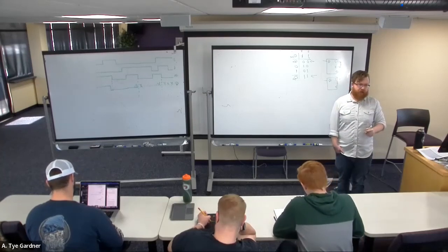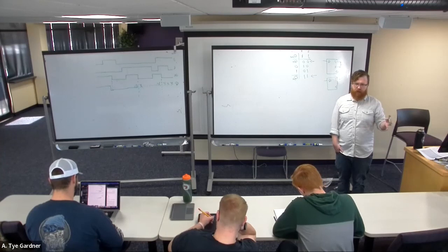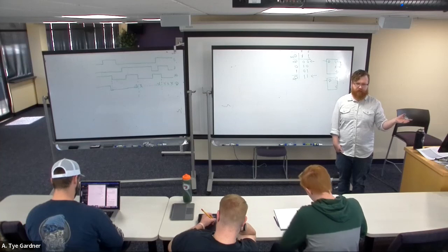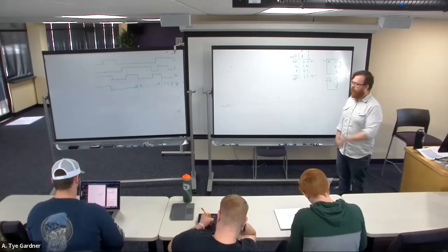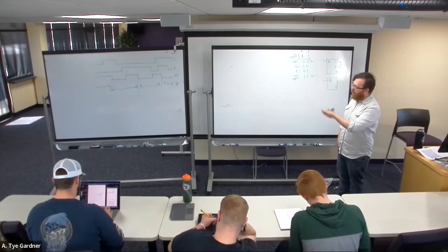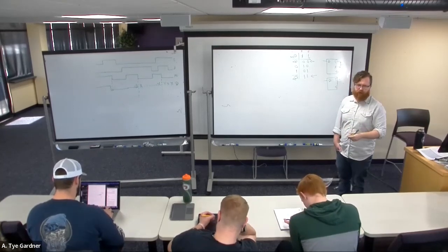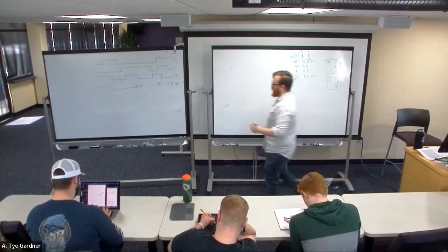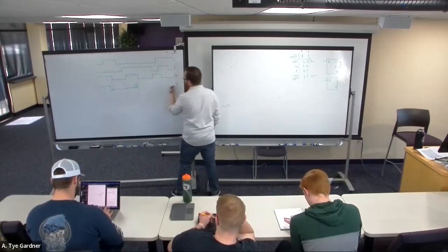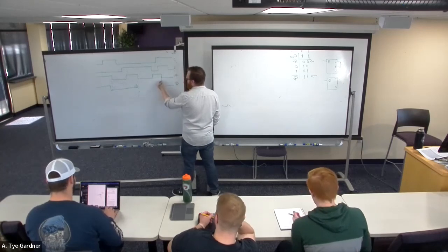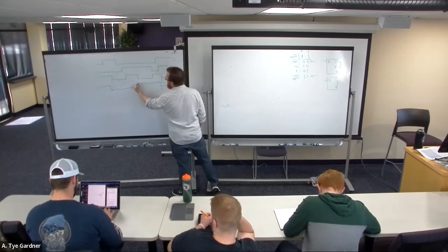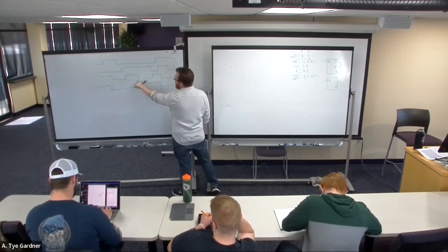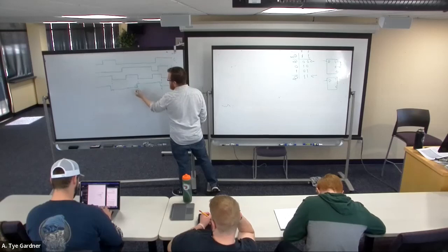So I'm just looking for the rising edges and I'm setting them based on the value. If you don't know, put X, right? If it hasn't been set to anything. Sometimes in the questions I'll say, assume it starts at 0, in which case, if it started at 0 and then we toggled, it would go from 0 to 1. Which is to say, I can draw that. If I said, assume Q starts at 0, well then when I have 1, 1, now I toggle. And then the next rising edge is still set to 0.